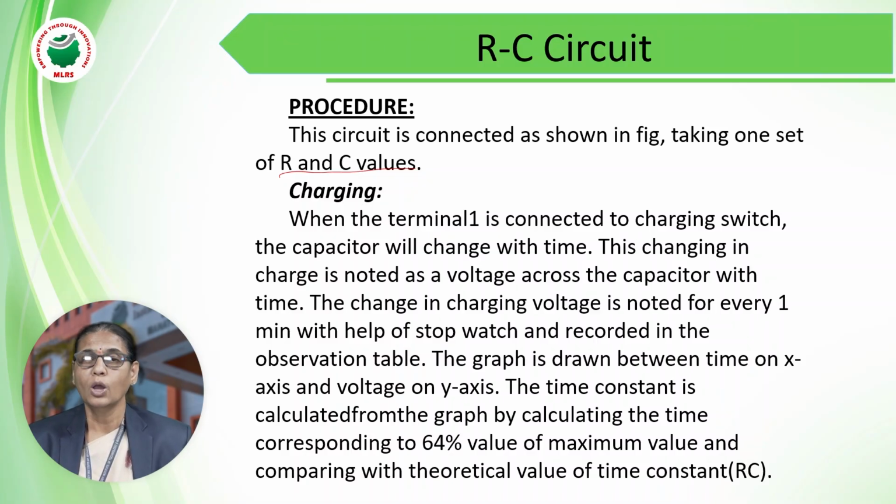Then after noting down, you switch on the switch. Once you switch on the switch, automatically the capacitor starts charging. When the capacitor is charging, note down for 1 minute, let us take 1 minute as the duration. In 1 minute, how much voltage is generated across the capacitor? Then at 2 minutes, how much? Like that till 10 minutes. Let us assume for 10 minutes we are charging the capacitor. How much charge is taken in that capacitor?